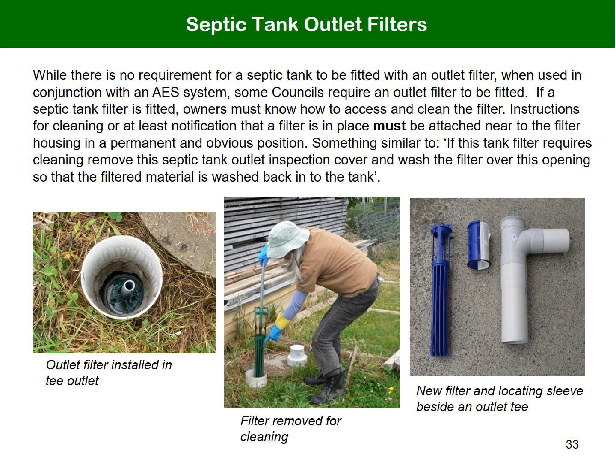While there is no requirement for a septic tank to be fitted with an outlet filter, when used in conjunction with an AES system, some councils require an outlet filter to be fitted. If a septic tank filter is fitted, owners must know how to access and clean it. Instructions for this procedure must be made available to both initial and all subsequent system owners. Instructions for cleaning, or at least notification that a filter is fitted, must be attached nearby to the filter housing in a permanent and obvious position.